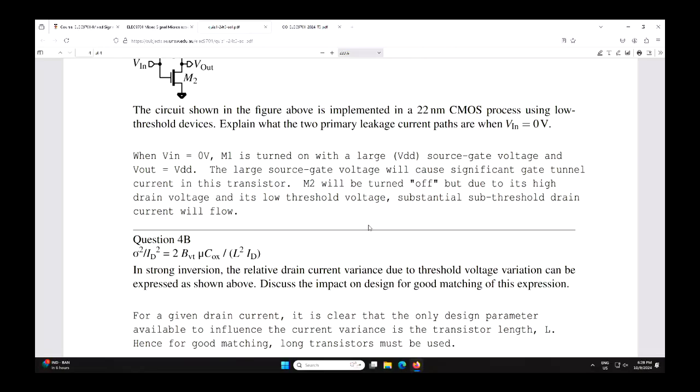If you need to have a certain noise, then that means you need to have a certain current. So very often the current that you need in a device is kind of the non-variable in determining transistor dimensions. And if that's the case, then it's the opposite way: you can think of that as a fixed thing, and the dimensions of the transistor as something that can change. But that obviously only works during the design phase, when you're determining the transistor dimensions.